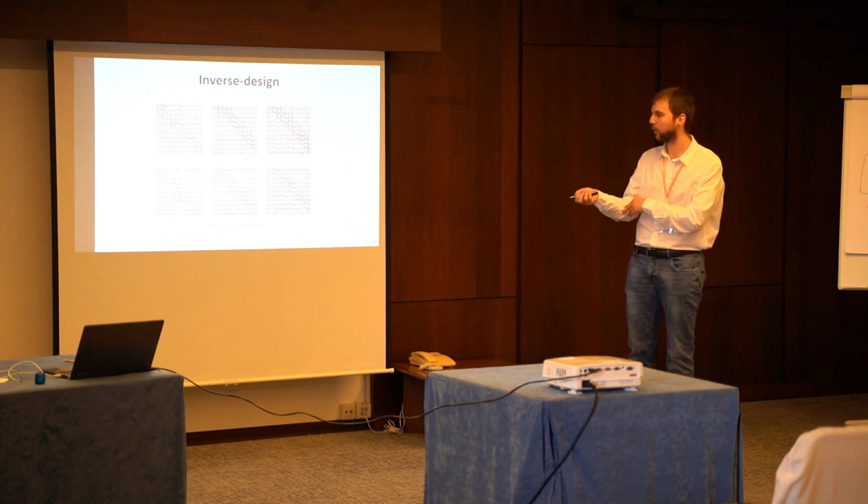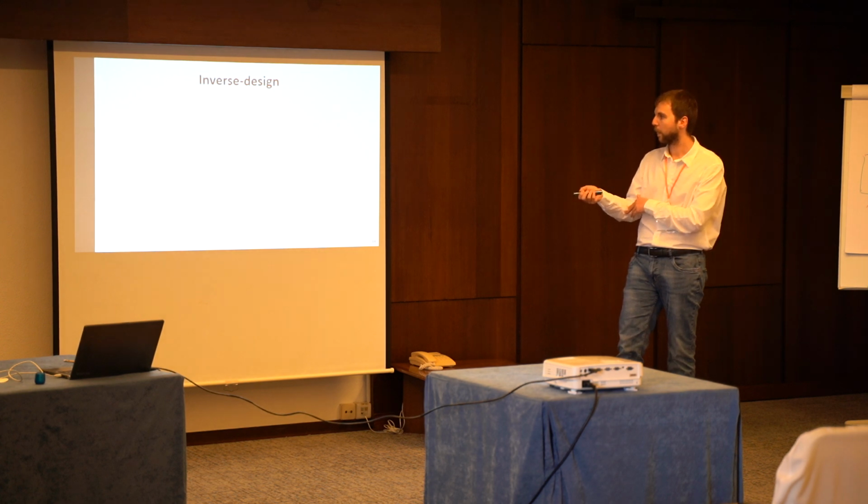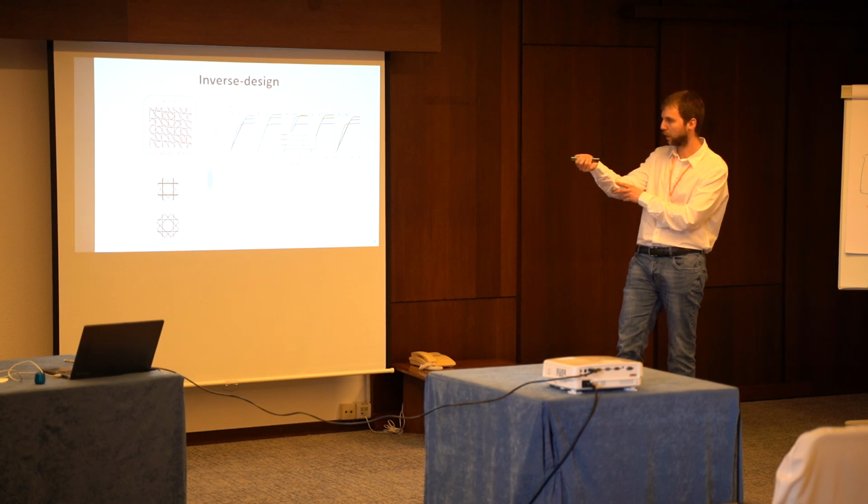Here are some patterns, and we see some 45 degrees periodic patterns. Then we want to evaluate the performance of the best design candidate at 0 degrees, and we compare it with the sponge designs. From the stress strain curve here, we see that the red curve, our architecture, outperforms the sponge designs in terms of maximum stress.